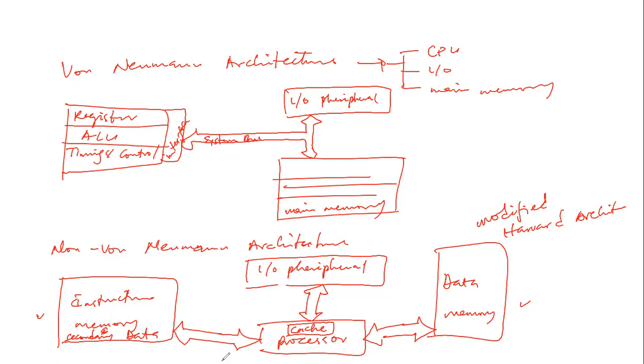And then in this architecture, the processor is accompanied by a small yet very fast memory storage called the cache, like we say it here. So when the processor is executing from the cache, it accesses a pure Harvard architecture. And when it is accessing from the back-end memory, it acts like a pure von Neumann machine. So you see that in modern devices, the modified Harvard architecture is preferred.